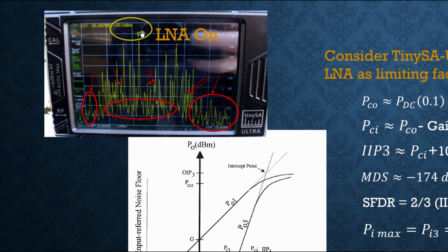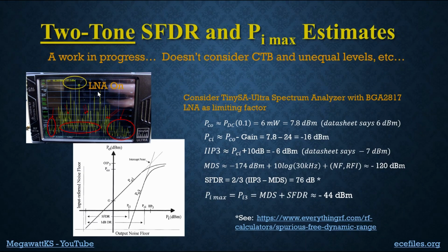Well, we definitely got one signal bigger than minus 44 dBm. This is minus 20 at the top, 10 dB per division, so this signal is also above, and this signal is also above. This signal's below, but if it's weighted together with this one, the average is still above the minus 44. So a lot of these stronger signals here can be creating intermods. And in fact, even more can.